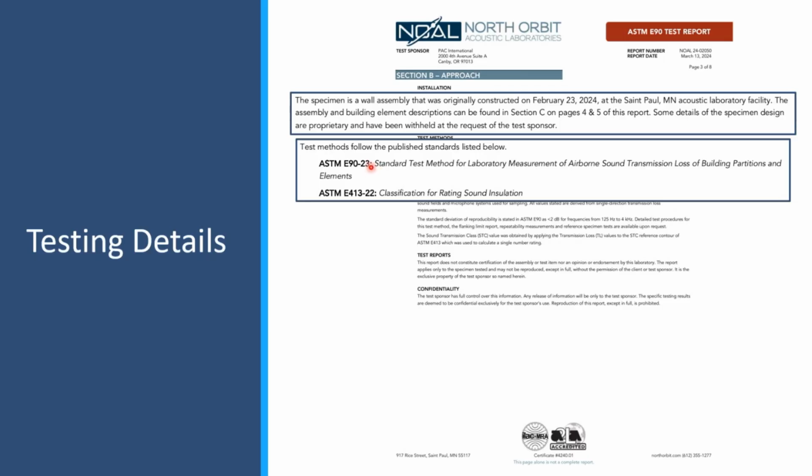We're working on a bunch of standards at ASTM and making a lot of changes to a lot of standards. Not all of them really substantive changes, but there are some things like in some of the field measurements, we're changing how you do the background sound level correction. That could slightly change your results, changing some of the reporting requirements and these different things. So it's important to get some idea of what version of the standard was used, and it's a good quality check. Like, is the lab using the most recent version of the standard?